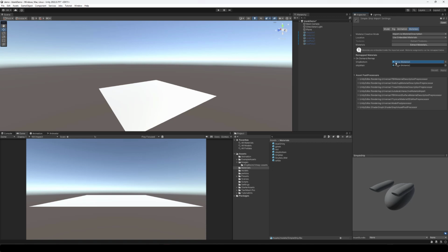So for this class, and in general really, I recommend using materials in Maya to indicate which things are which material, wood versus metal, for example, or repeated tile versus not repeating tiles, that kind of thing. But then in Unity, don't extract the materials. Instead, create your own in Unity or Substance Painter and drag those into the material slots in Unity. Unity will have access to the different material slots.